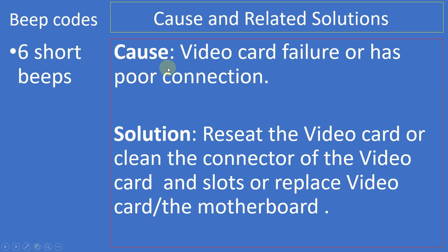6 short beeps, the cause is video card failure or a poor connection. So the solution is to reset the video card, or clean the connector of the video card and the slot, or replace the video card or the motherboard.